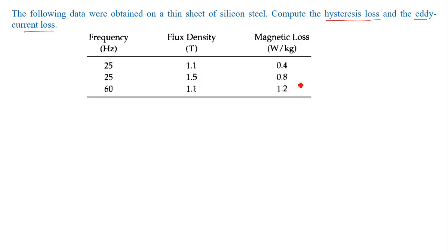It is possible to measure because we can find this magnetic loss just by putting a wattmeter across the device whose magnetic loss we want to find, under no load condition, right? We'll talk about it more in the transformer part, when we study it.